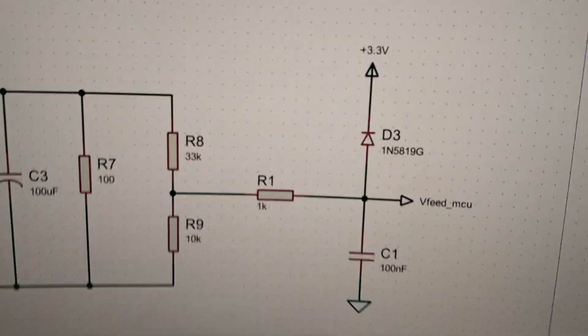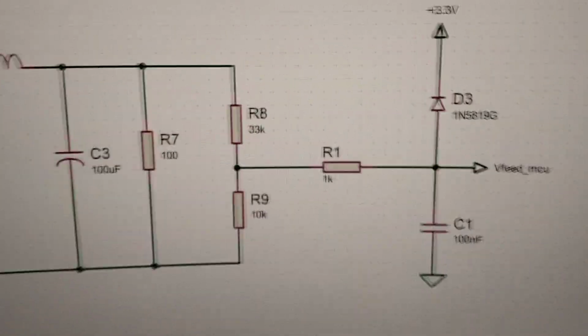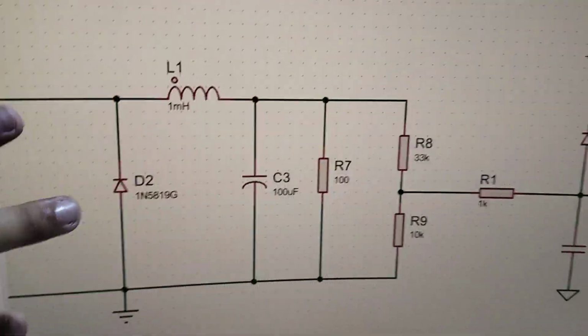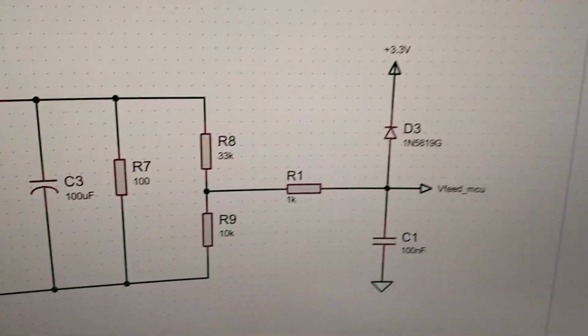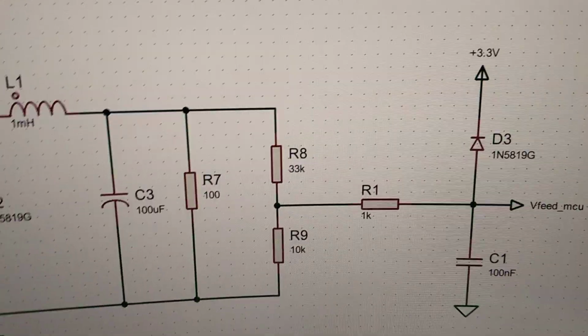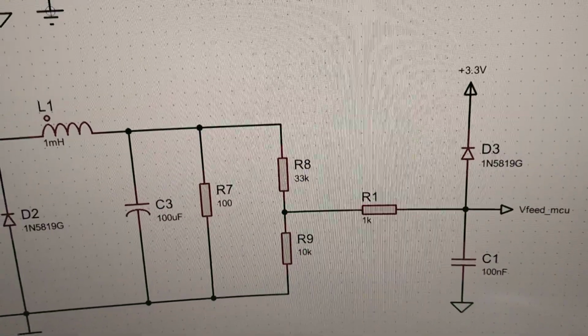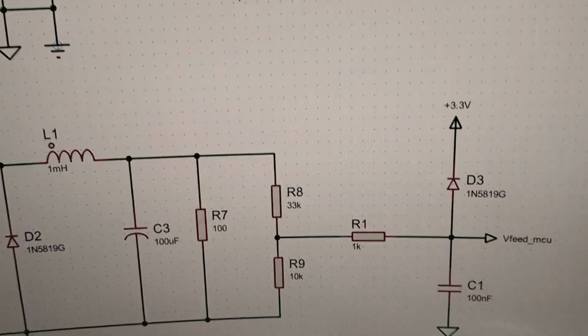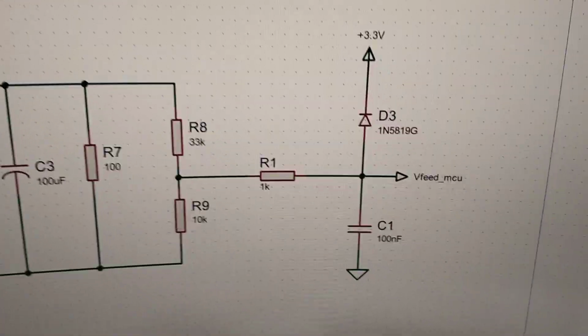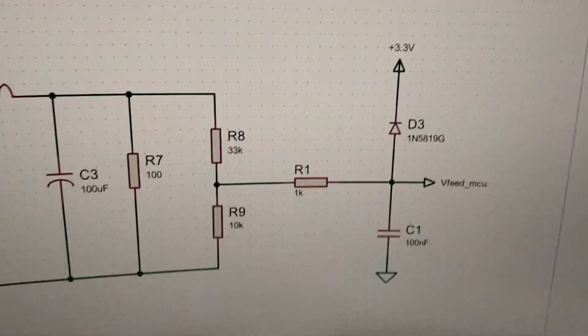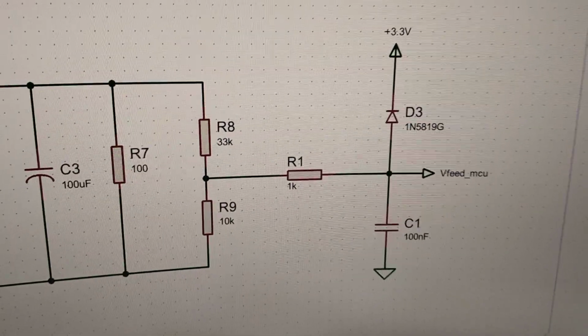And since we need feedback, as I said, we're going to be sensing the voltage, and our input voltage is 10 volts, right? And of course that's much too high for a microcontroller to directly sense. It'll just destroy it. Generally the ADC, which is an important part of what we're going to be doing, you can go check out the video which I did before this. It's on ADC. This is the basics of it.